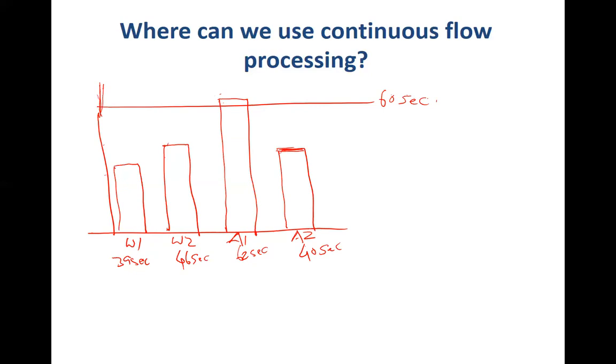So in total, these 4 processes are taking 187 seconds, right? And we know that we are currently going beyond the takt time, so we have to fix this situation overall. Now, we want to understand approximately how many people we actually need to establish the 60-second takt time if our total time right now is about 187 seconds.